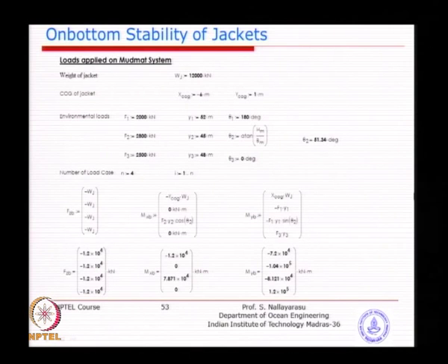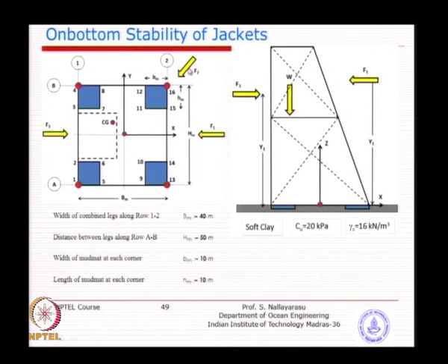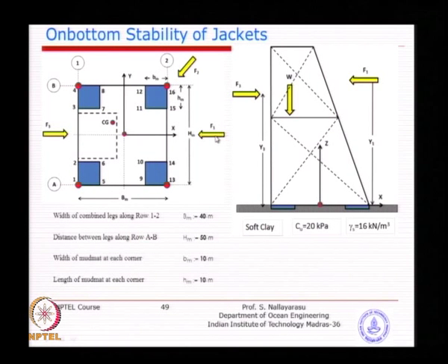Basically for this particular case, this one is resolved in x direction as well as in y direction, so that you can combine them, but F1 and F2 are not going to be concurrent, they will be applied in a different timing. So, maybe wave is coming in this direction for some time and wave is having another direction. So, you should not combine F1 and F2.